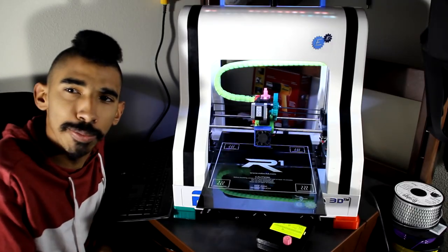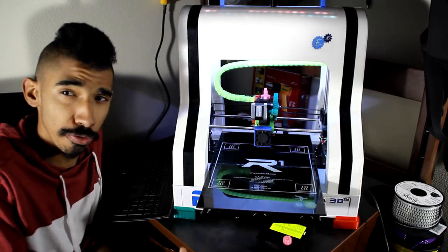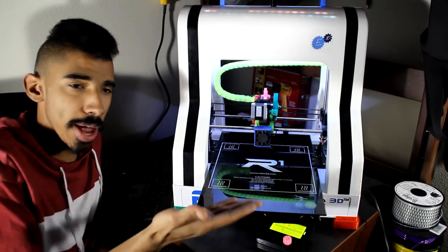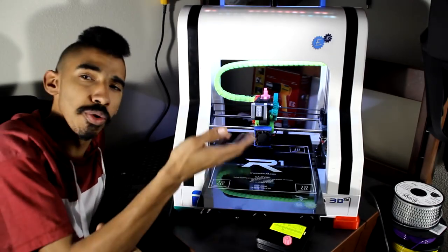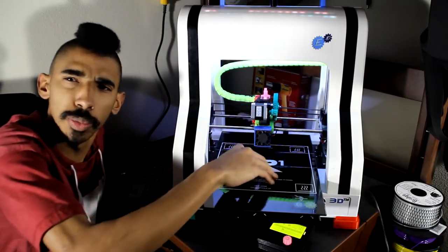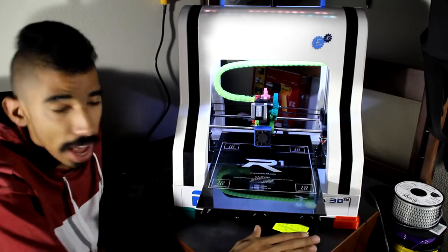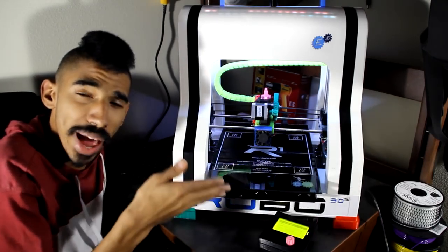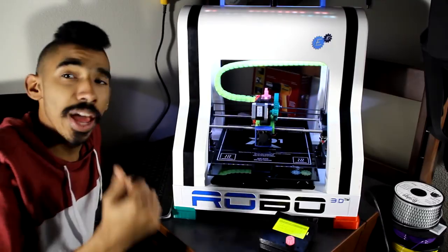This is a beta test being done by the Marlin firmware developers. It's a pretty cool program. It raises the Z-axis, it moves the extruder out of the way of the print space, then you can touch up what you need, of course change the filament, and then as soon as you touch the LCD controller, the print will go back to its exact position and resume.